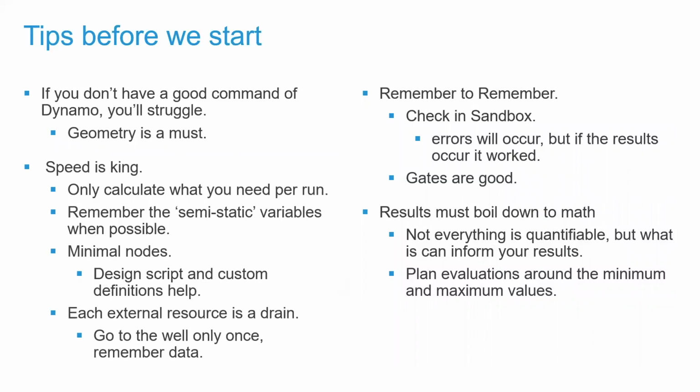So don't waste your time there. Remember as many semi-static variables as possible. Use minimal nodes, DesignScript, and custom definitions and custom nodes really help out on that front. External resources are a super drain. Every time you have to go back to the well to get more water, it takes more time to fight the fire, right? So ideally, bring a bigger bucket or bring the right bucket.